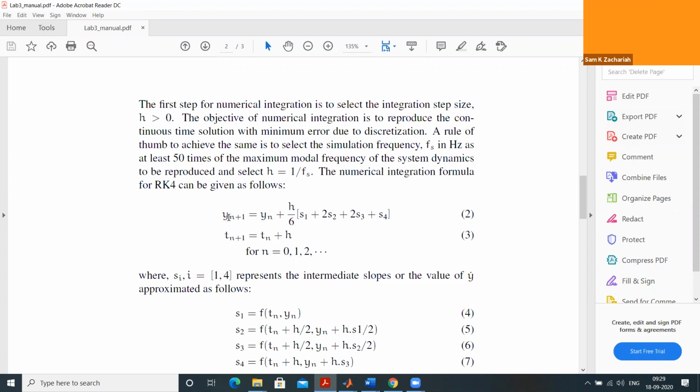And y0 will be the initial value of all the states. Suppose the gimbal is at null position with 0 velocity. Then what are all the states involved? You know that the states are deflection as one state, angular velocity as another state, and states of the controller. If you are using a PI controller, the integrator has a state.